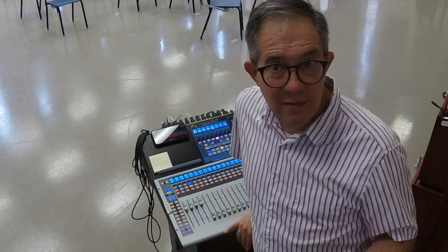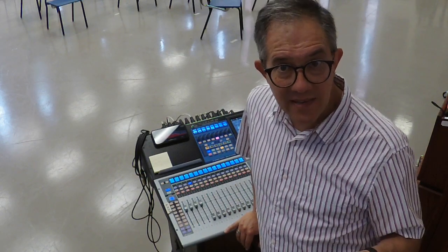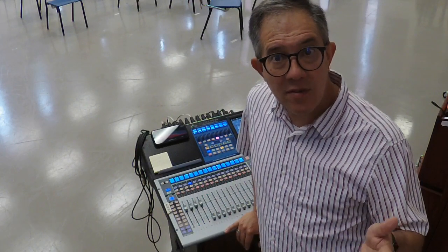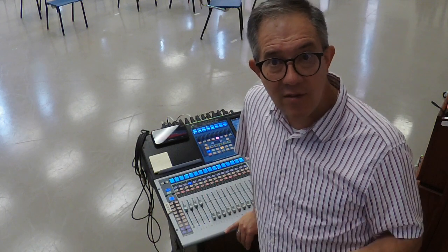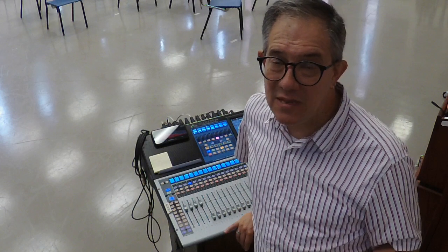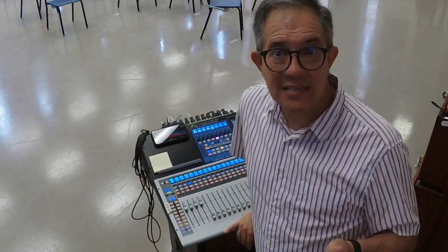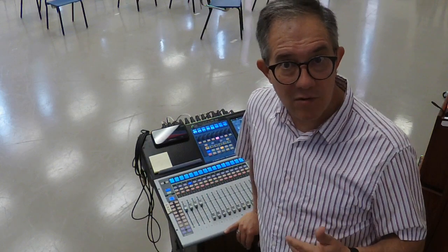So hopefully this is something that's useful. Hopefully you're seeing some of the connections from the basics we've talked about with frequency and octaves, and also decibels and how that logarithmic scale makes a difference. Most of us are not going to need 40 dB of gain on the mic inputs, but you might need that much input to actually get it to feedback really regularly.